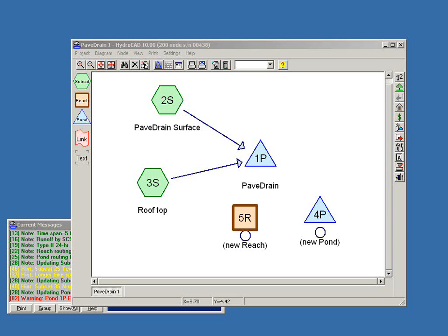Sure. I will give the cost of the paved drain system around the country generally gets delivered to the job site, and that's assembled into mats, for between $6 and $7 a square foot, just for the standard gray units, matted together, delivered. Installation on top of that runs $1 to $2 a square foot.